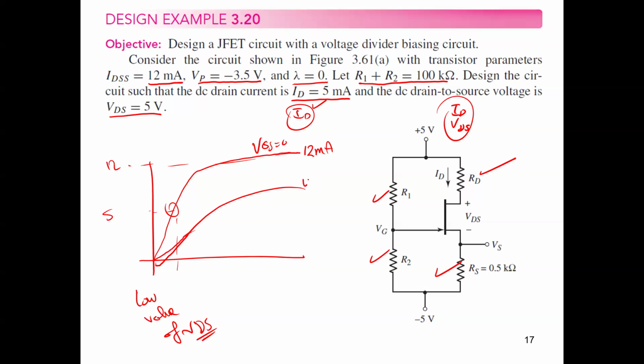Another curve here at VGS equal negative value, not 0 value. In this case, the current would be like that, for instance, 5 milliampere at V drain to source equals 6 volt. Okay, so this is my preliminary expectation before solving the question.